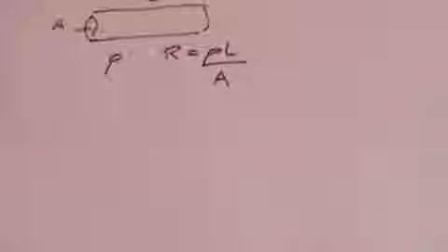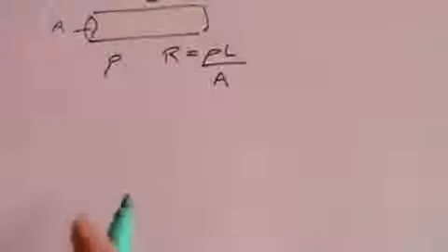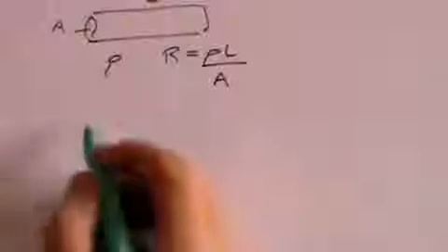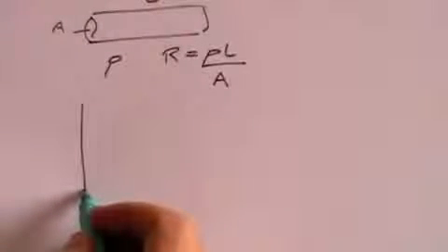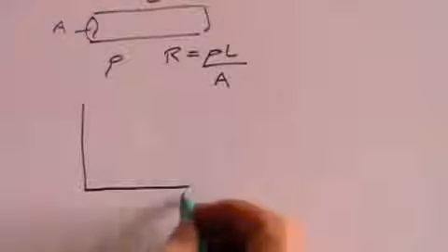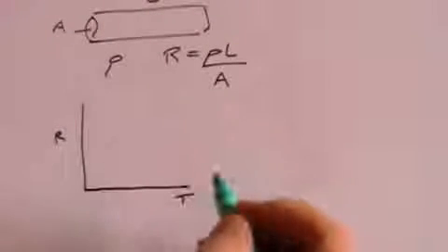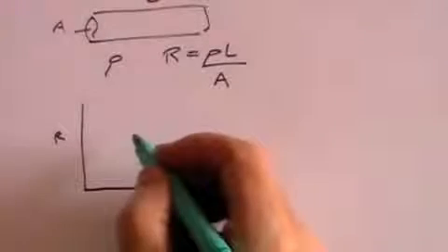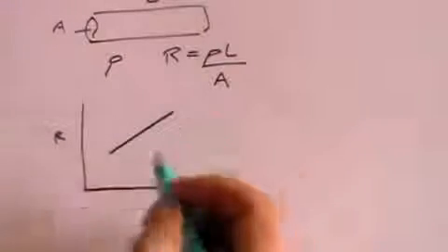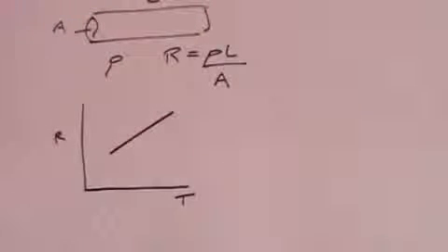Now, in fact, Ohm's law is not something that works all the time because it is heavily temperature dependent. By that I mean that if you plot temperature against resistance, you usually find that resistance increases as the temperature increases.